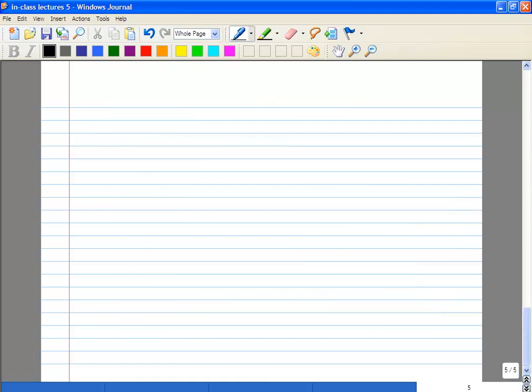Okay, so let's look at what kind of capacitances you have. You're interested in, let's say, drain bulk and source bulk capacitances. The other ones, for example gate drain and source drain, are all related to your gate drain or gate source overlap capacitances. You can't do too much about them; that's limited by the process. But the junction capacitances, you can do something about them. If you look at these junction capacitances, they actually have two components.